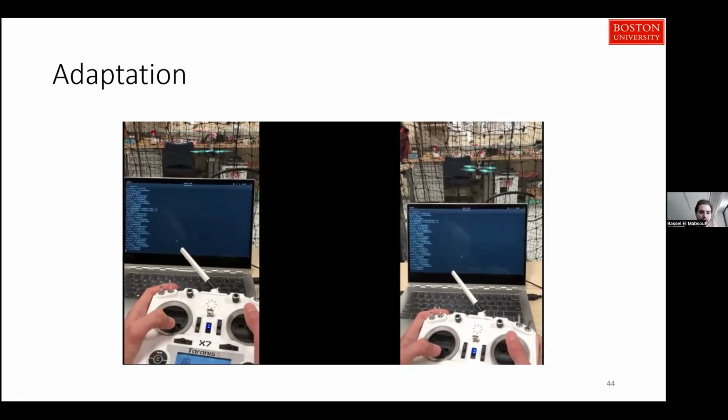People, when they're flying the actual drone, most of the time it's not moving. And because of that, the set point is usually very close to where the drone is. So the reinforcement learning algorithm learns something wrong here. It learns how to follow set points that are near, but it forgets how to follow set points that are far away from it. And this is due to the fact that we have no guarantees with respect to this. There's nothing that says that it will follow our intention.